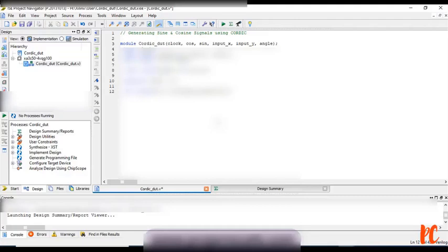Now I need to copy those arc tangent values, which I have then converted into binary. So I will be placing those binary values. So here is the generated table of arc tangent values. These are the values which are being stored in the lookup table. You can observe, for example, if you consider with respect to 45 degree, the arc tangent will be 2 power 0. Similarly, for the next coming degrees, we will be declaring with respect to arc tan inverse of 2 power minus 1, 2 power minus 2, 2 power minus 3 and so on. So those converted binary values are these values, okay.